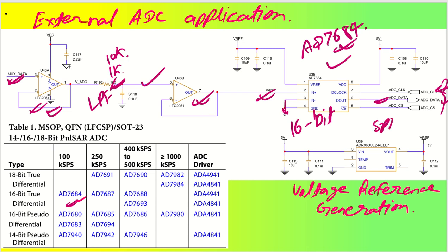So that will be SPI master in slave out. This is how it is going to get connected to my SPI MISO to ADC data. And ADC CS can be connected to SPI NSS, that is the select lines, so you can use this particular understanding. If you have several other ADC signals or something like that, then you can utilize this. Otherwise you can always put it either high or low based on the requirement that you need.